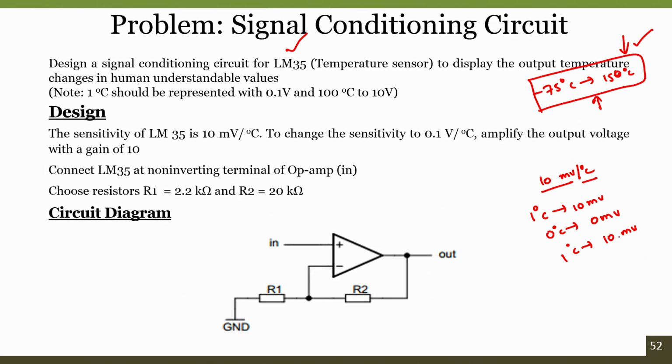Now, how do we design, and what is the need of a signal conditioning circuit here? Since we are planning to interface to an ADC, where one of the data acquisition devices, the DAQ, has an inbuilt ADC, which is an 8-bit ADC, let us say, directly connecting the output of the sensor to the ADC will not meet all the levels of the ADC. So though we can achieve better accuracy as well as resolution of the temperature, because of limited usage, because of an improper signal conditioning circuit, we are unable to display with a very good resolution.